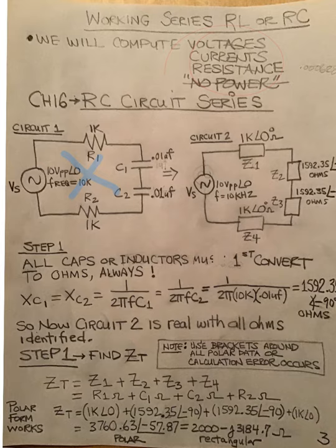It doesn't matter what the component locations are going to be. The battery will supply the same amount of current regardless of location. And being closer to the battery will not mean that your voltage will be bigger. If you remember in chapter 5, series circuits, the largest resistance gets the most voltage. Well, we've graduated to impedance.